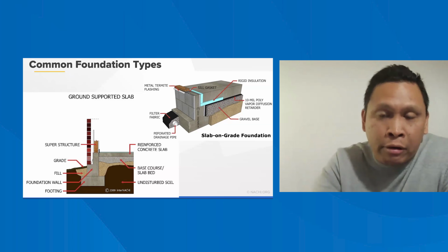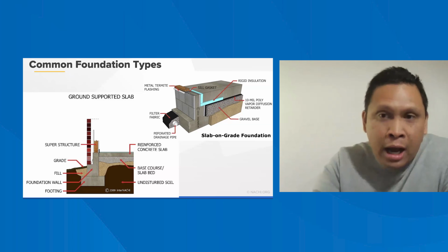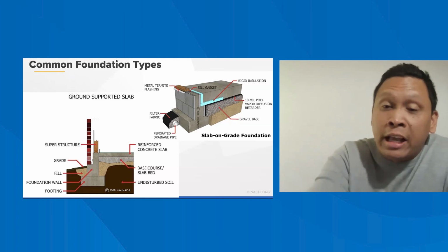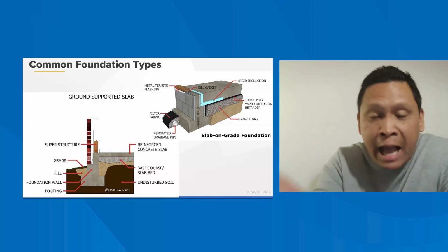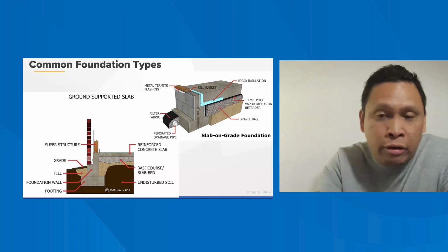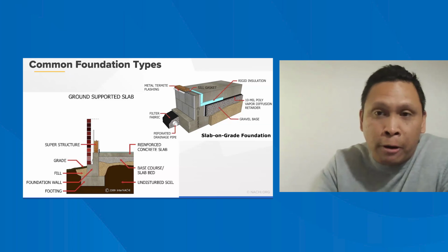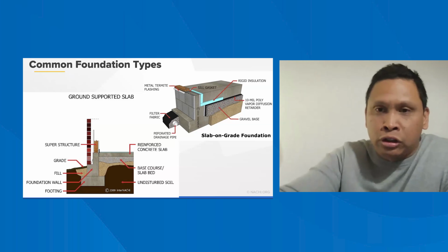And now we all know that the bottom part of the wall is called the bottom plate. So why is it important to have a sill gasket there? Polyethylene, actually. But why is it important to have it there? Because it acts as a capillary break. So as the water moves upwards through the foundation wall, hopefully that sill gasket, polyethylene foam, it just gets rolled out.